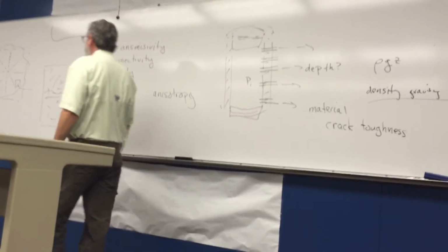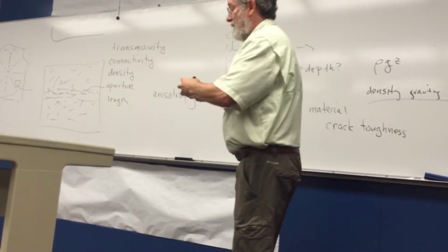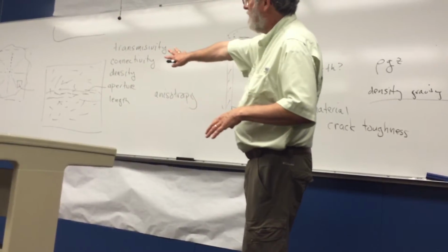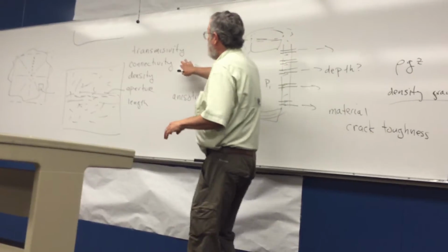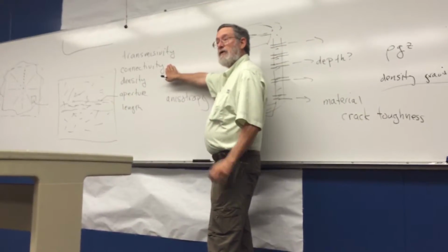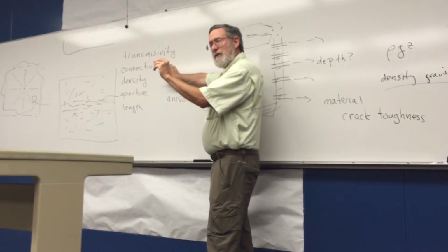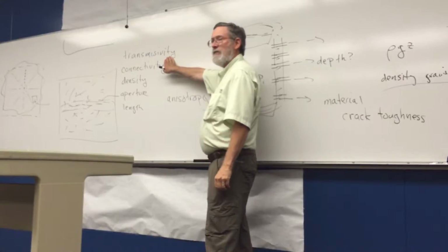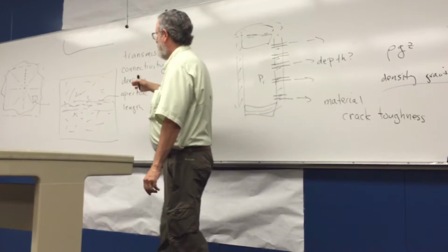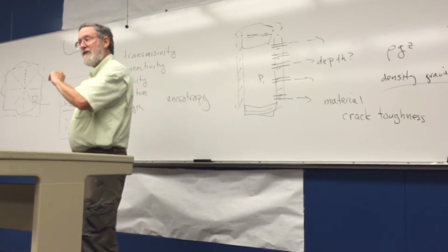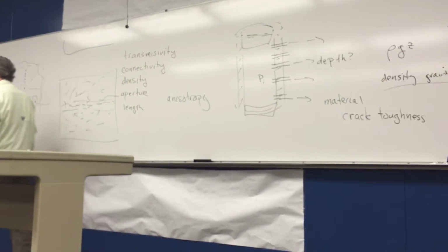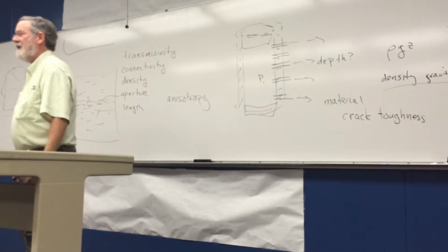But the main thing you're trying to do is to extend the fractures. You're trying to cause these fractures to link up so that they're better connected. You're trying to prop them open so that they stay open, so that you have good transmissivity in the system, so that you can get back as much of the fluid that you injected as possible. It's impossible to get it all out. In fact, most of the time your recovery is not so great. And then start producing the hydrocarbon in that particular system.